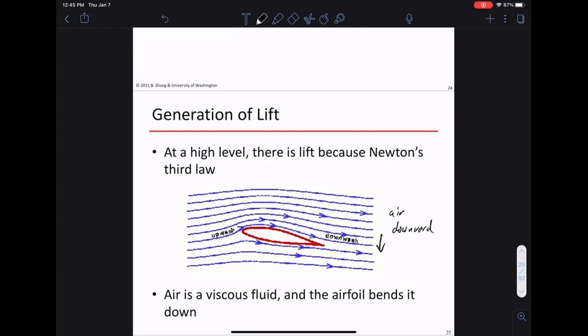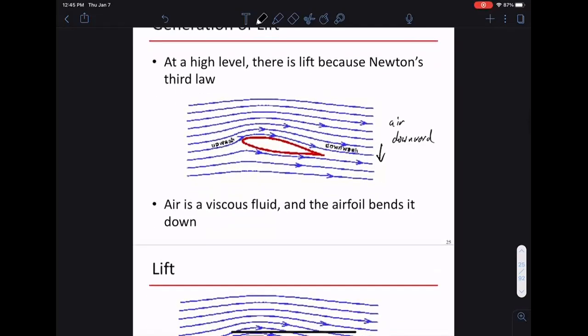And the reason is because air tends to hug the shape of the airfoil. So the shape is important. This is not saying the shape of the airfoil is not important, right? The shape of the airfoil contributes quite a bit to how efficiently lift is generated. But the reason it contributes is you want to bend air in a more efficient way. So that bending of air comes from the shape. And if you bend it very efficiently, you generate more lift. Right? But it's not necessary to have this shape to generate lift.